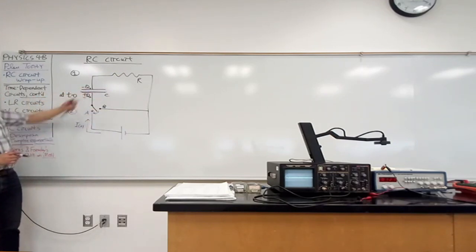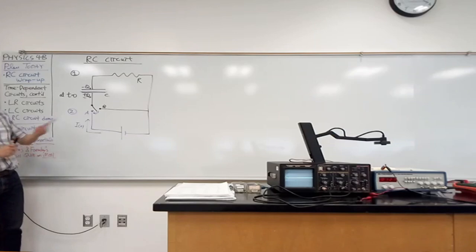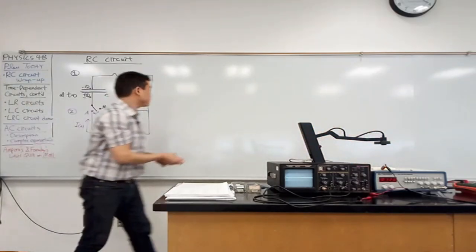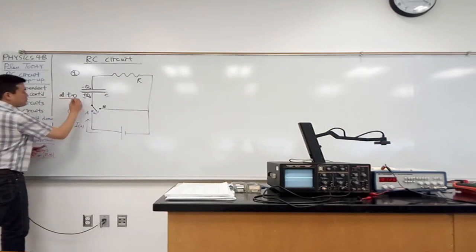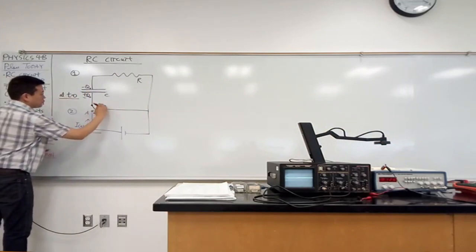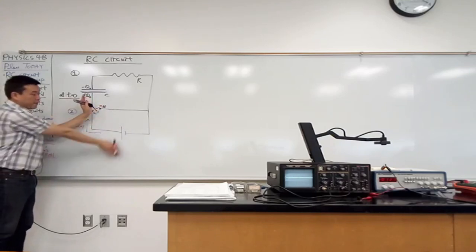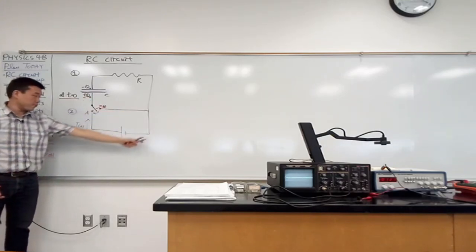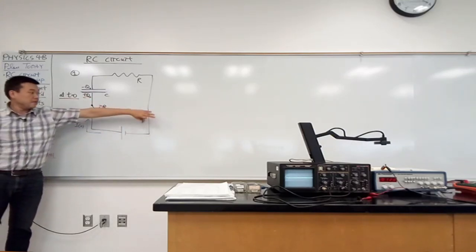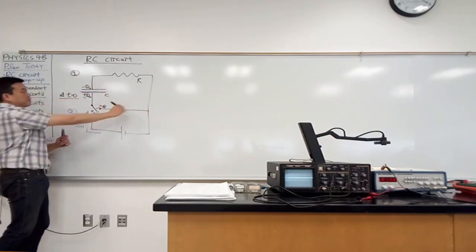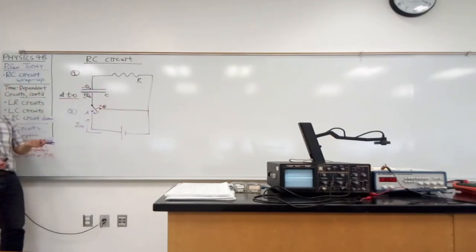And once it's charged up, then we could switch it around and say at time equals 0, we are going to close this switch over to the B side. And then the battery, we can ignore it. There's no current through this entire branch. We can just ignore that it's there. And then we have that simpler circuit that I initially started out drawing.